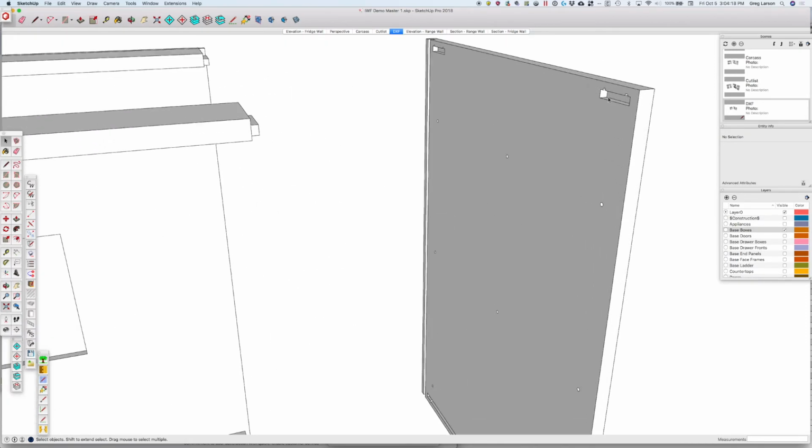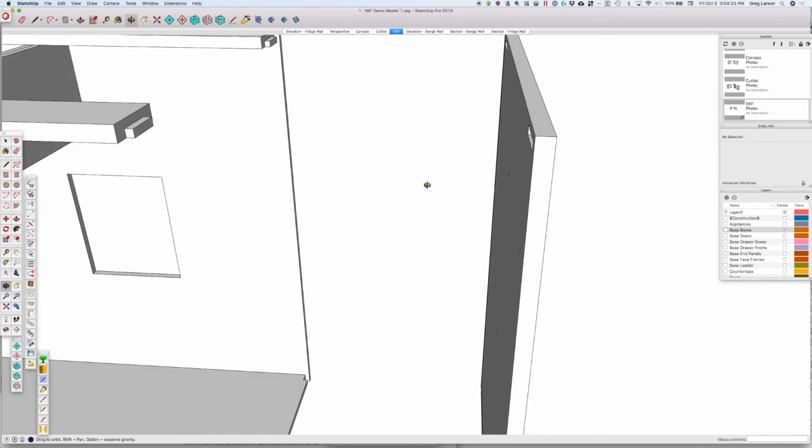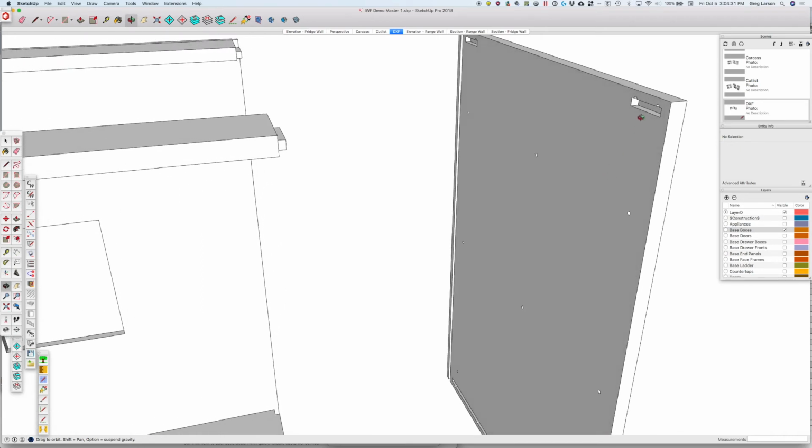All right, so we've got a constrained pocket here, and if we made this tenon the exact same width as this pocket, remember when we're cutting this pocket, it's not going to be square, it's going to be a round bit, and it's going to have a radius on each end here.